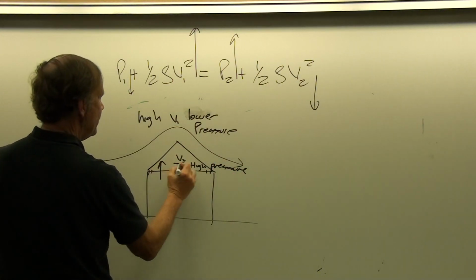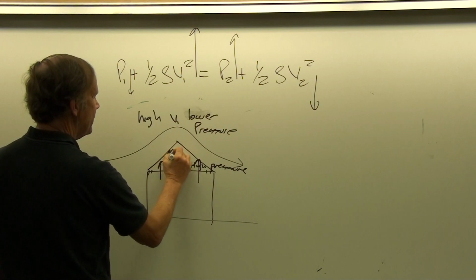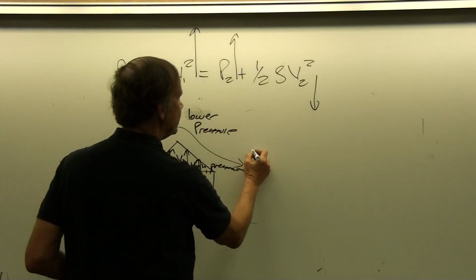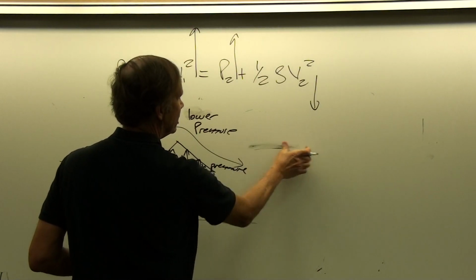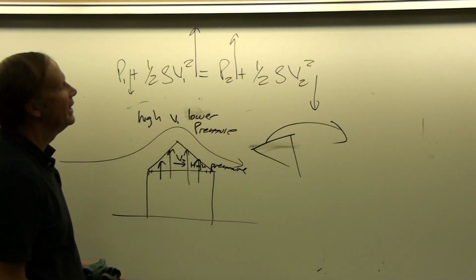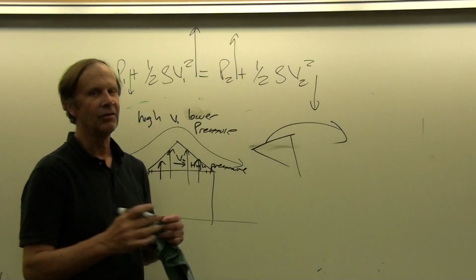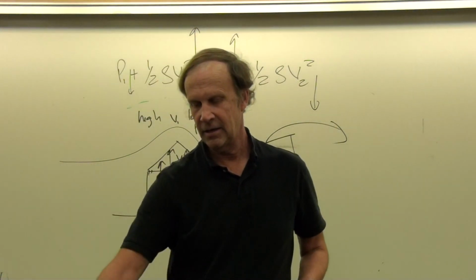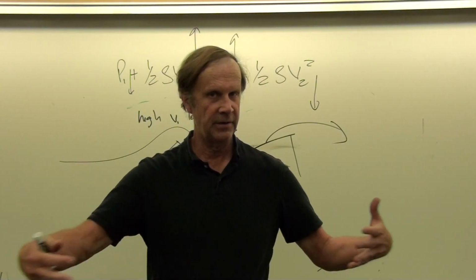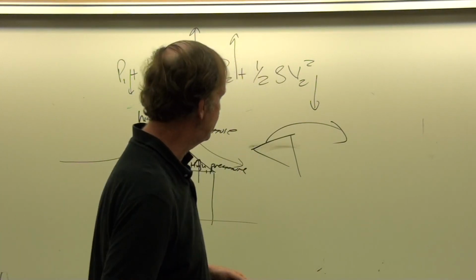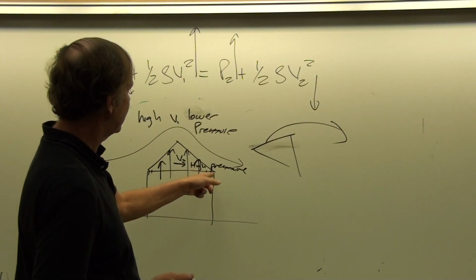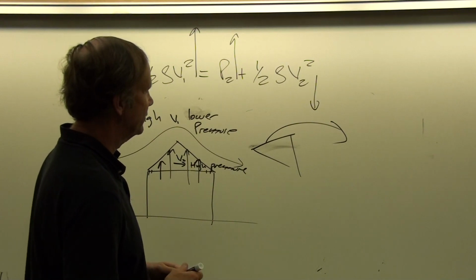And so that high pressure then will tend to push up on the surface of the roof, and so that roof can just take right off. If it's not held down properly, the roof is gone. Okay, and so that's happened in a whole neighborhood where new homes had been produced all at the same time by the same construction company that had used substandard materials to anchor their roofs.